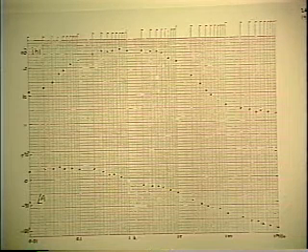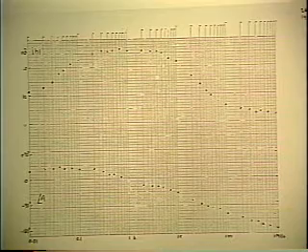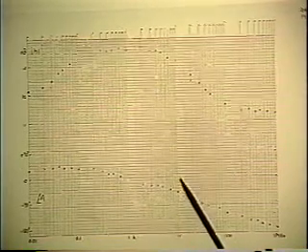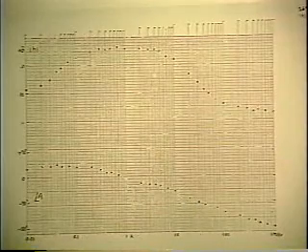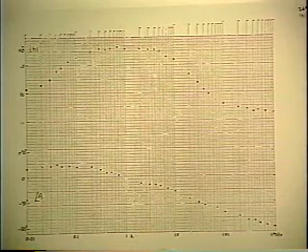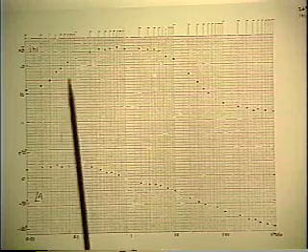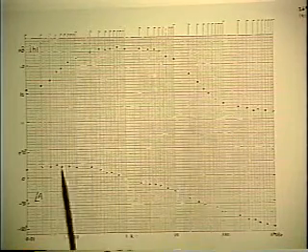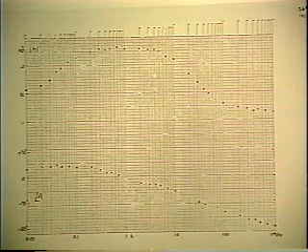And typically measurements that we make are frequency response, which would be magnitude and phase for some system. Let's suppose for the moment we don't know what the system is. So we get raw data. We get a sequence of points for magnitude and another sequence of points for phase.